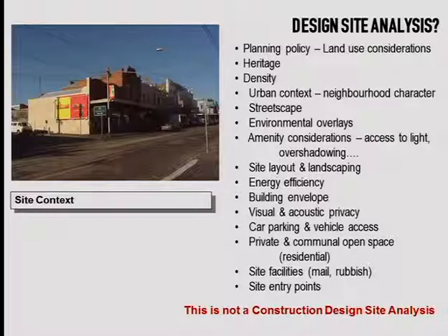You're looking at environmental overlays. What sort of amenity do you have to take into consideration? Am I going to overshadow a neighbour? Do I have access to light? Is my building going to be orientated to the north to get maximum solar benefit? So you're looking at these energy efficiencies. You're looking at the framework of the potential building envelope that you can build within.